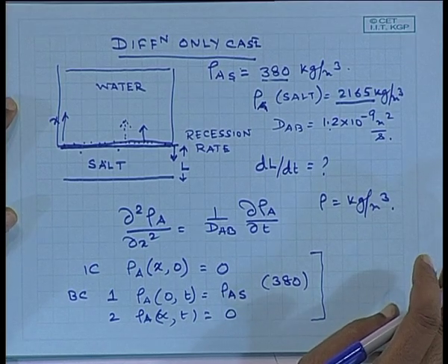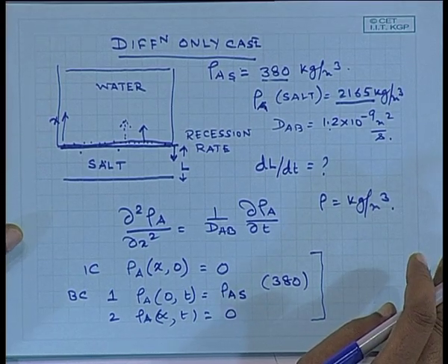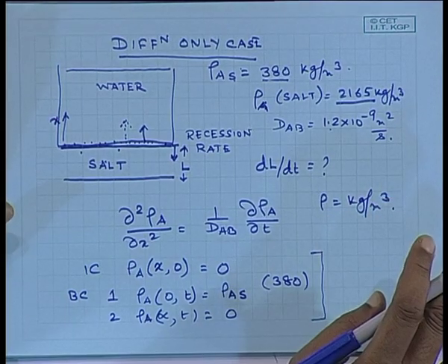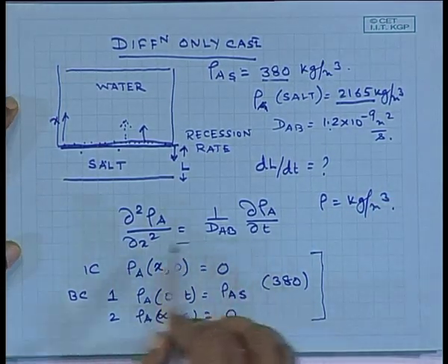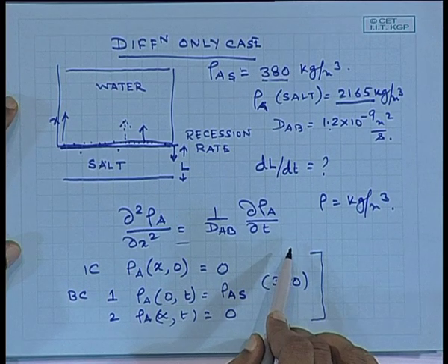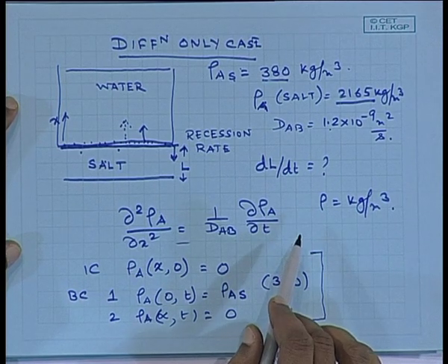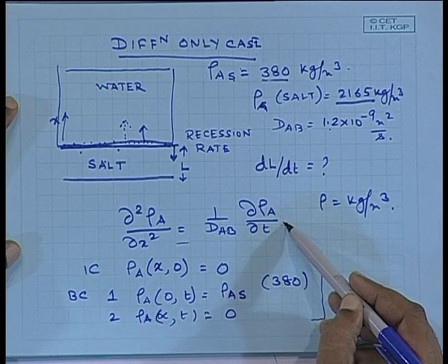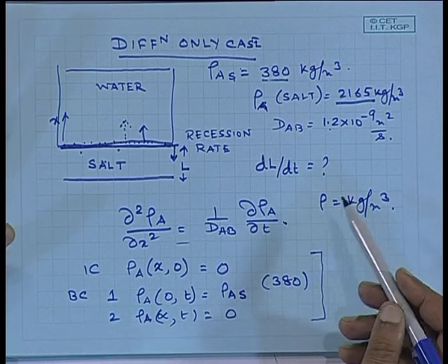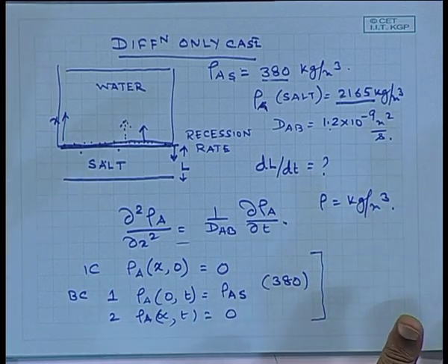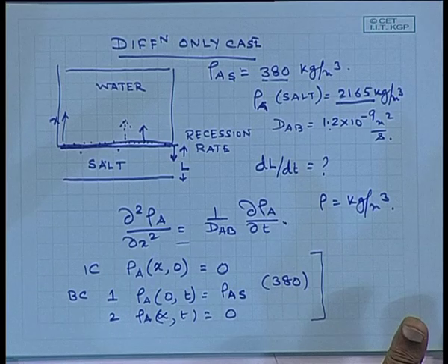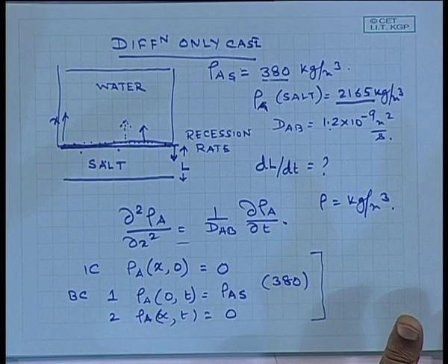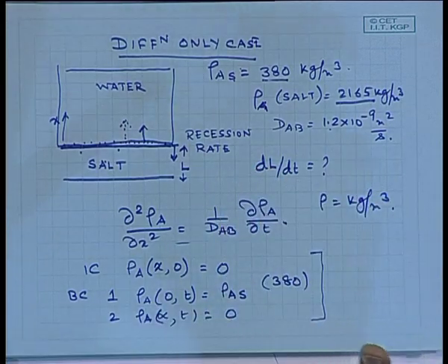And what I would encourage you to do is, you do not have to derive the solution. For any number of PDEs, the solutions are already available. What you have to check is, you have done this case for heat transfer. You have a semi-infinite body which is at thermal equilibrium. Suddenly, you change the condition at one of the boundaries and find out how the temperature front is progressing